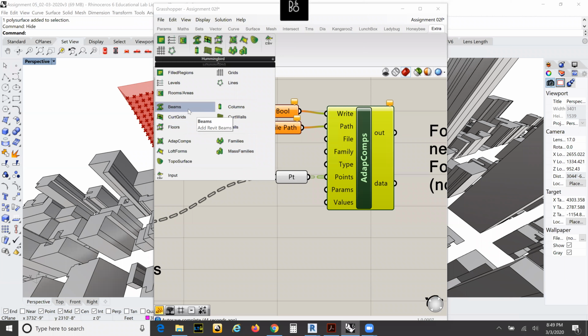One reason why we're doing an adaptive component instead of a curtain wall is, again, the rules that Revit has to follow. The rules that dictate the curtain wall family are that they always have to be 90 degrees. We can make a curtain wall not have 90 degrees in Revit, but we have to edit that geometry, which is very time consuming if every one of those is a unique piece.